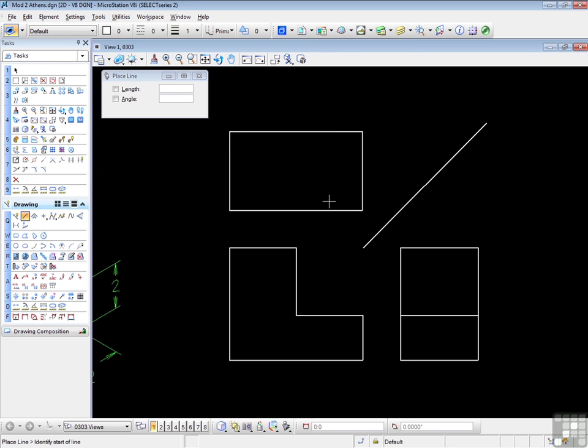Let's add the final line, which is, of course, this one here. So I need to find that point. F11, O key, drag upwards, enter, N, find that point, drag upwards, enter, N, and find that point. Now, this enter, N combination is an obvious choice for adding to a single shortcut key or even a function key.